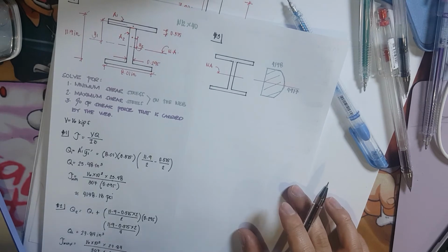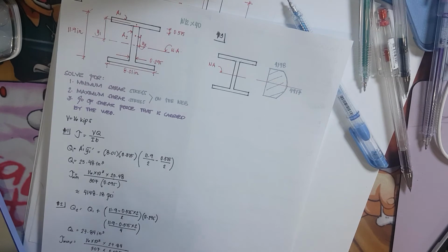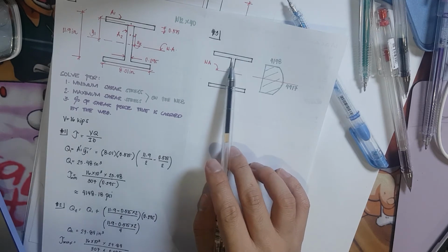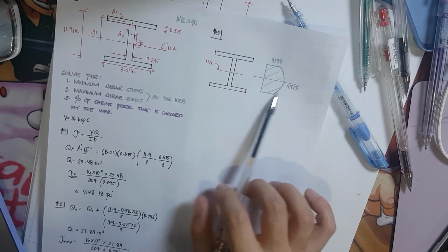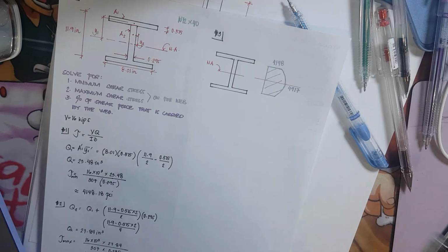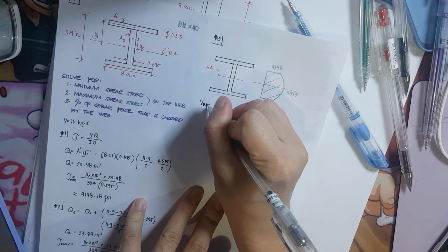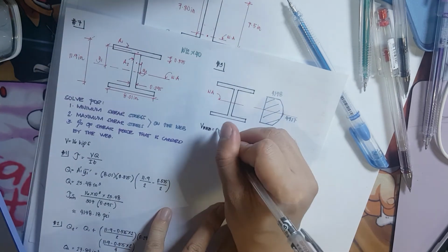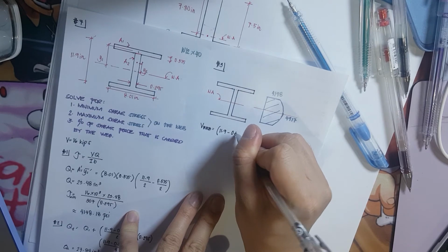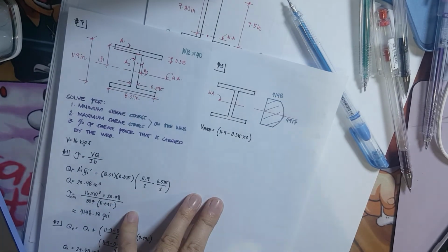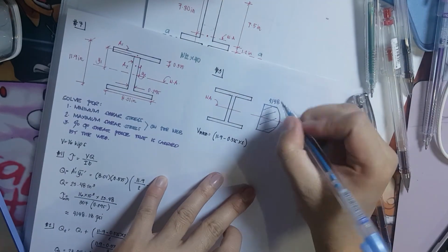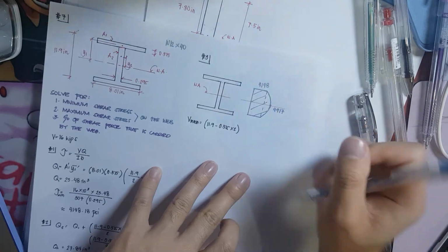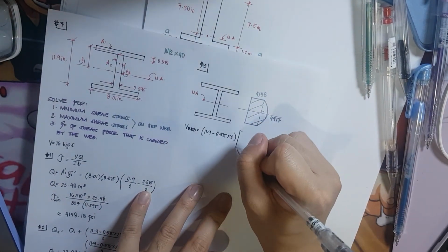Okay. So to determine the percentage of shear force that is carried by the web, it is simply the area of your web times the area of your shear stress. So the shear of the web is equivalent to the area. So ano yung height nito? That is 11.9 minus the thickness of the flange. So 11.9 minus 0.515 times 2 because we have 2 flange. Yun yung area. Then for the area here, let's consider this as a square or rectangle rather. Then here is a parabola.